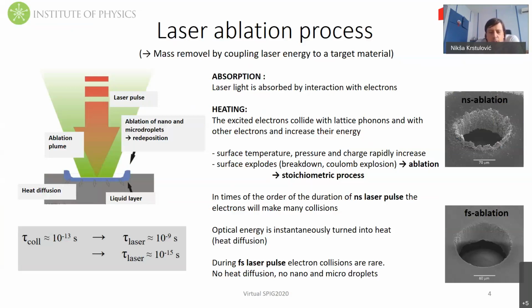If we talk about nanosecond laser ablation with nanosecond laser pulses, then the delivered power is in the range of megawatts. If ablation takes place with femtosecond pulses, then we are talking about terawatts. So that is a very, very energetic process, and irrespective of the bonding of different materials in the lattice, the stoichiometry will be preserved.